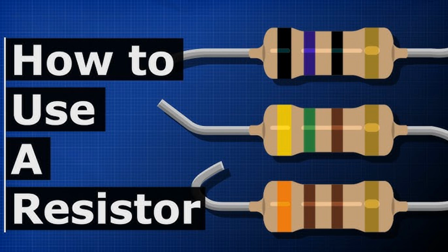Saturation region. Purpose. The transistor acts as a closed switch. Biasing. Both the base-emitter and collector-base junctions are forward biased. Example. In switching applications, such as in digital logic circuits, the transistor is biased to enter saturation when turned on, ensuring it conducts fully.